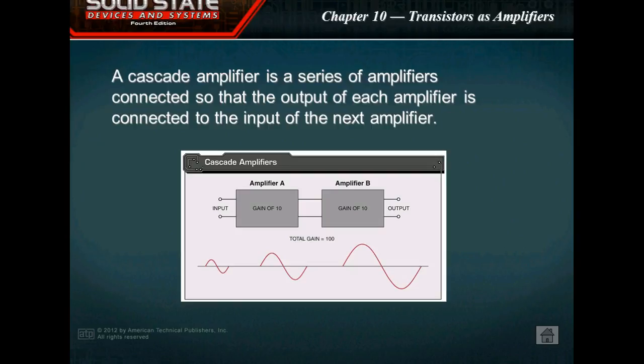So what they're showing us here, if this amplifier gives us a gain of 10 and we feed that into another amplifier that has a gain of 10, what would be the total gain from input to output? Not 110, it's 100. So I say like I'm going to triple your salary. When we go through stages of amplification, what we do with gains is we just multiply them together. We don't add them. Right, you understand?